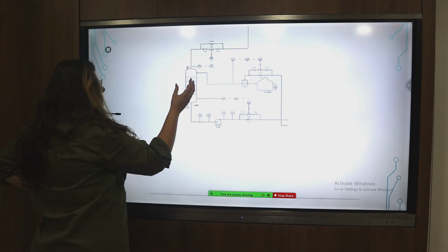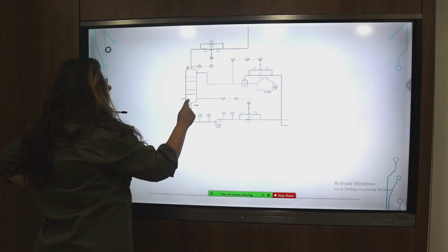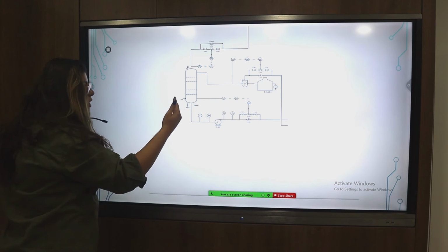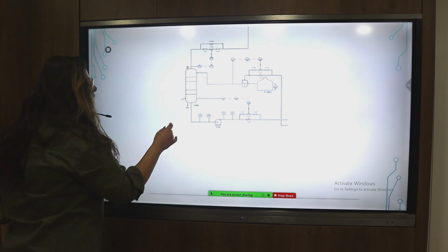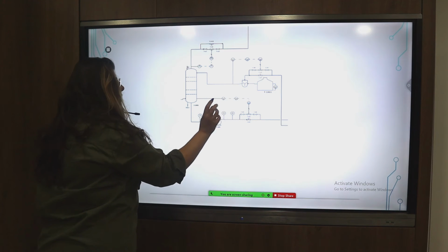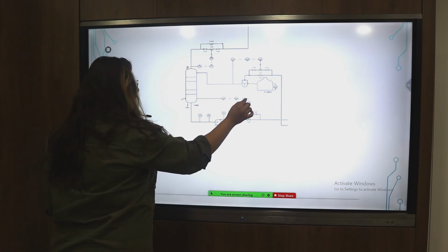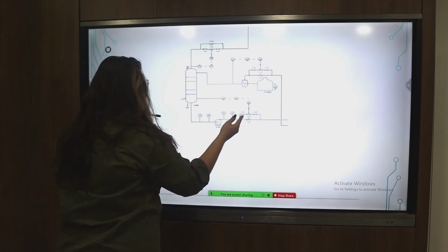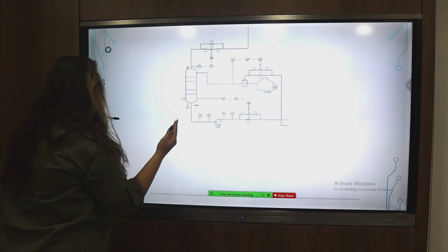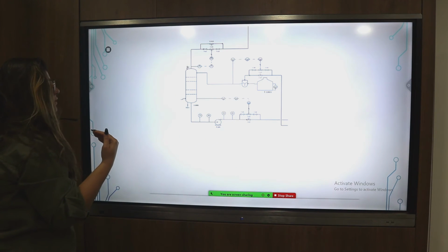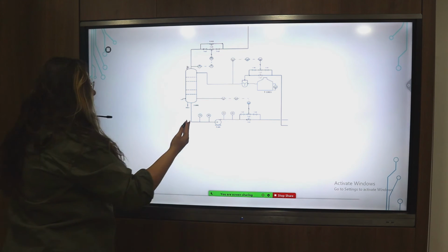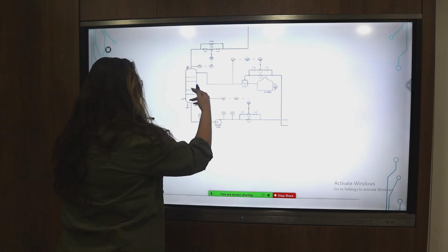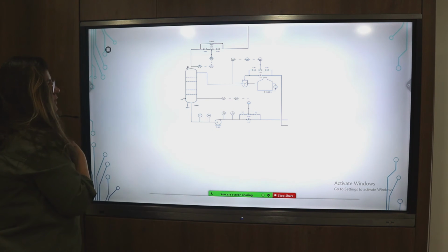Now, if I have a column that has both liquid and vapor in it, the liquid level must be at a certain height. It cannot exceed or be less than this height. So in here, we'll add a level indicator. Again, level transmitter, level indicator controller. It will control the valve of the liquid flow leaving the absorber. If the level of the liquid is too high, it will order the valve to release more liquid leaving the absorber, therefore decreasing the level, and of course, vice versa.